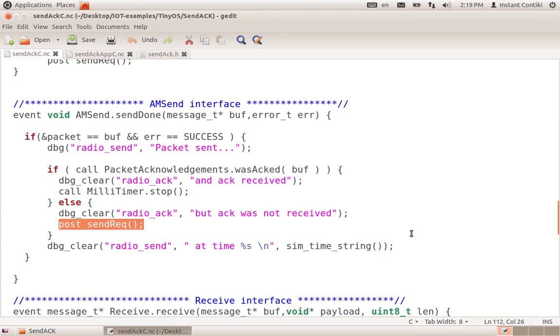This is for the transmitter side. Okay, it should be clear. We start a timer. When the timer fires, we put the data in the packet, we transmit it to node 2, and then we wait for the acknowledgement. If the acknowledgement arrives, okay, good. If it doesn't arrive, then we have to start another request. That's it. Let's see what happens on the receiver side, so on node 2.